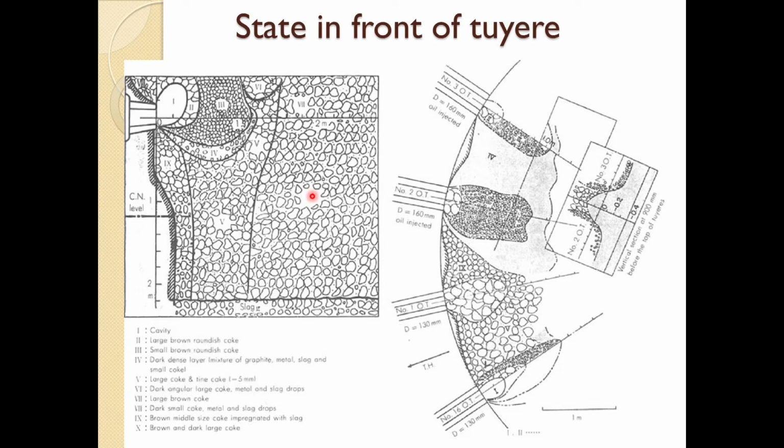And if you look at the top view of that, you can see the oxygen level is almost zero by the middle of the raceway. So, all oxidation reduction has occurred by this. This is the oxidized region, and after that reducing gases start. So, CO2 formed reacts with carbon and CO starts forming, and in front of that raceway you have a higher size coke, and at the side of it, because lots of abrasion and other things are occurring here, fines are generated which get deposited further down.